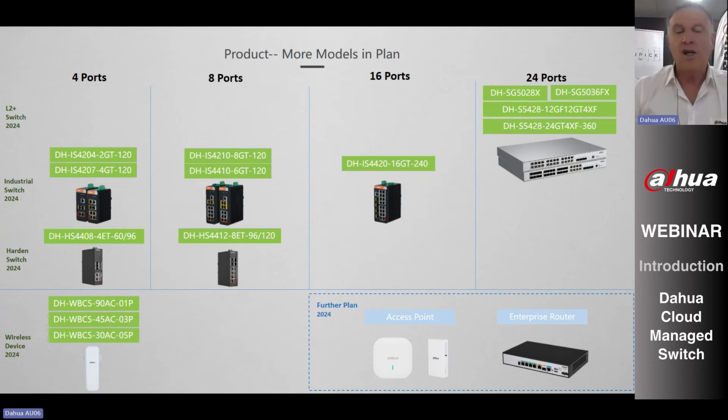especially in the Victorian heat lately. We just ran through a heat wave of mid 30s and high 30s. If it's 30 degrees out there and you've got a switch in an enclosed metal box, that switch could possibly go up to 50 plus, 60 plus degrees. You need to make sure that the switch you're employing for that particular project, for that particular system, can withstand those high temperatures. Well, that's what industrial switches, the hardened switches, are capable of doing,